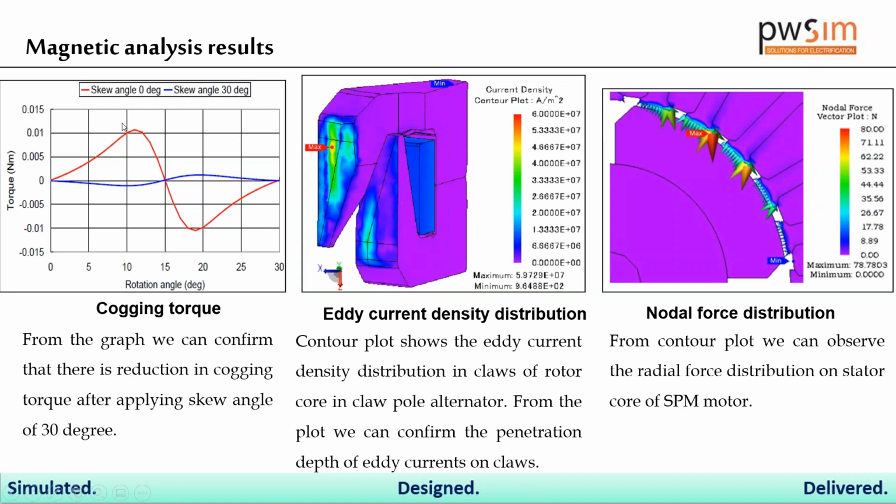So like I told you, how the cogging torque phenomenon happens and how it changes when the skew is applied. Skew is like you are tilting the stator or rotor configuration. You can do the combinations, different types of combination. The multi-slice function is available within the JMAG Designer window.